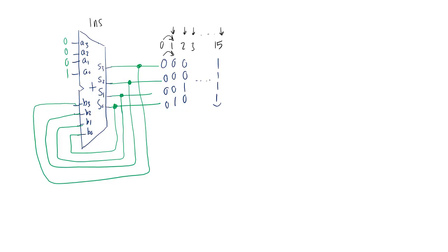It becomes a more serious problem when you think about the internal circuit of an adder. All of these bits are not actually calculated at the same time. So you get S0 first, then S1, then S2, then S3. So again, we get the problem of the asynchronous counter that we had, the first counter that we had.